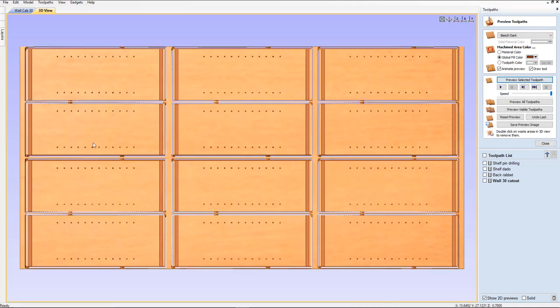And this looks pretty good. So all you'd have to do is cut those corners out with a jigsaw and use a router bit to trim that off. And this is good to cut. So right here you have enough to make 1, 2, 3, 4, 5, 6 wall cabinets. All you have to do is cut your shelves.